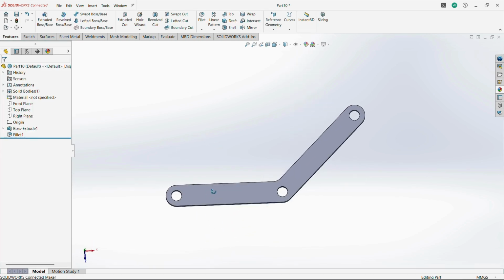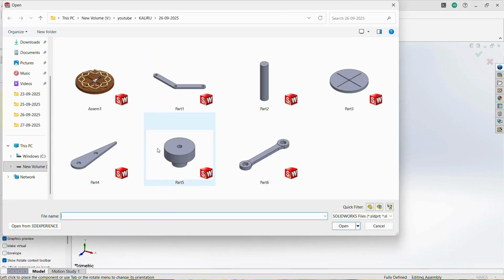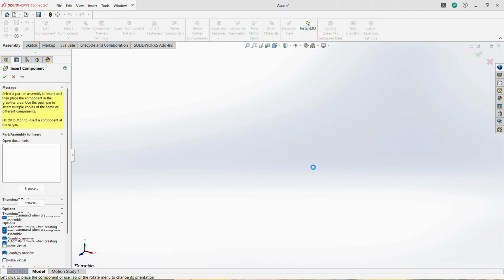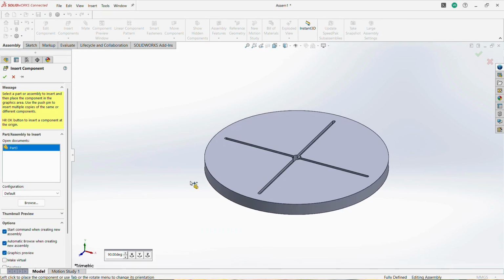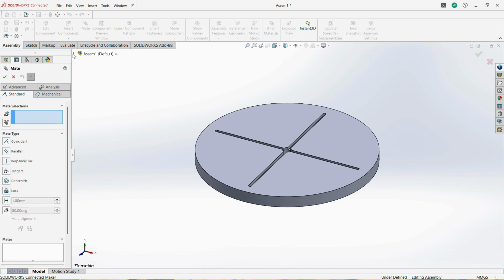It's almost created. Here we draw different parts in different part categories, but the main thing is the assembly. Based on this assembly only, we are able to get the kinematic mechanisms. Now choose this particular solid, that is part 1, the base part. Once it is positioned, right click and make it a float part, because we just fixed it based on the origin point.